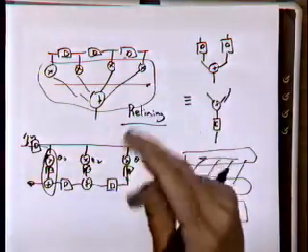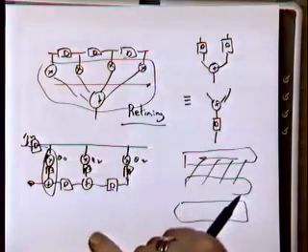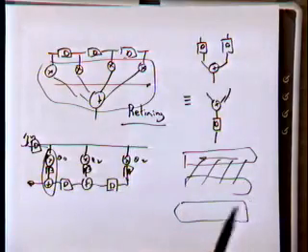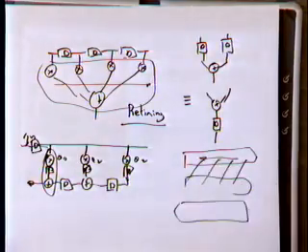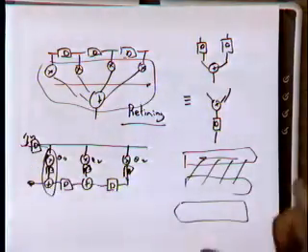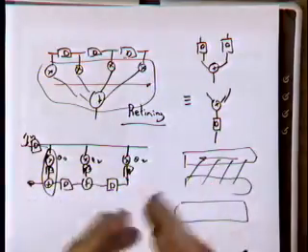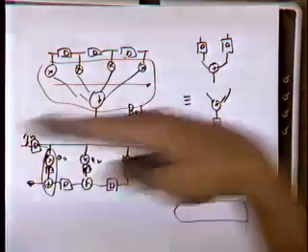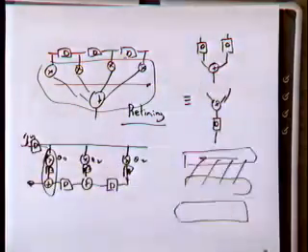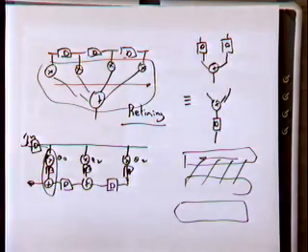I think it's actually better than doing a full Wallace tree in this case. A Wallace tree adder, a carry look ahead adder, is the tree structure. Now you just do partial look ahead. You make the complex gates to fan in of 4, to fan in of 2, and then you ripple through. It's a combination of ripple and look ahead, which is a very powerful scheme. A lot of people do this in companies. In a lot of microprocessors, that's what people do.